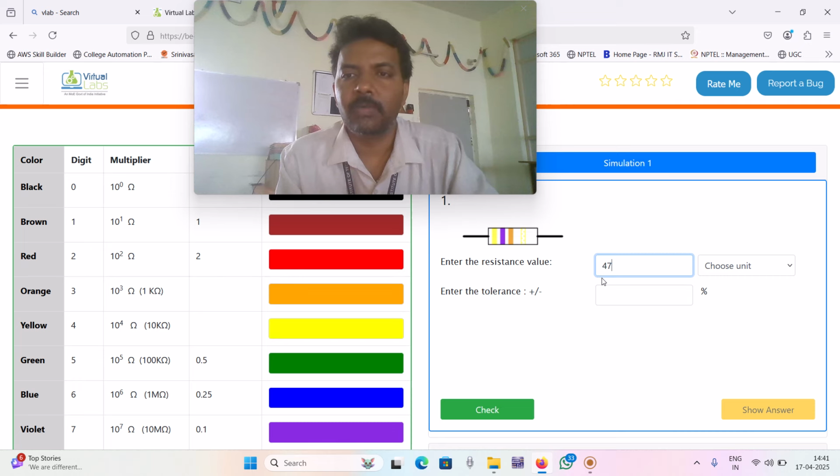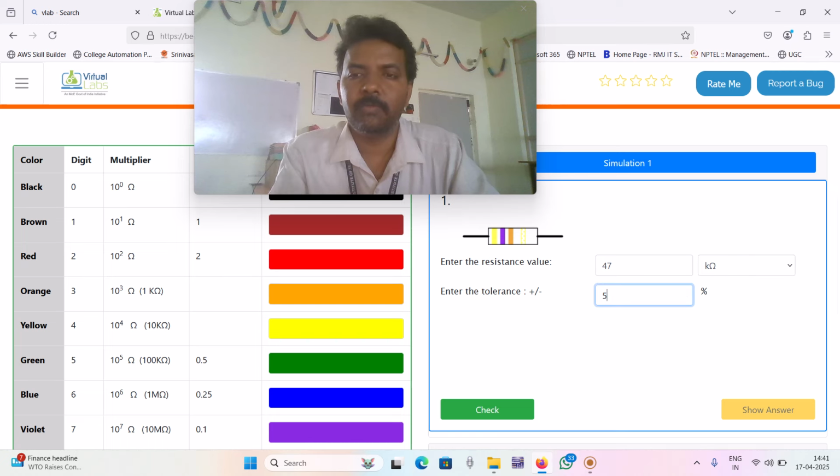That means 1K. So here we can choose the units, either ohms or kiloohms or megohms or gigaohms. So here we know that it is 47,000, that means 47 kiloohms. You can choose kiloohms in the sense it is 47, ohms in the sense 47,000. So here the tolerance is gold color, no? That is for 5.